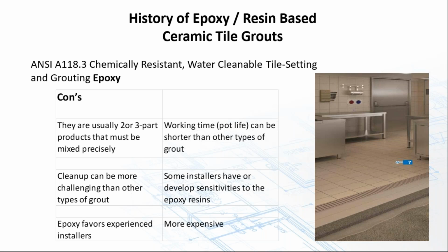Yes, cleanup can be a little more challenging than cement grouts, but if trained properly, it is not that much more difficult. It is a resin, and some installers do develop an allergic reaction to it. It can happen. They don't seem to be as caustic as what they were years ago. Yes, we still hear of once in a while somebody being allergic to it, but not as often as what it used to be.